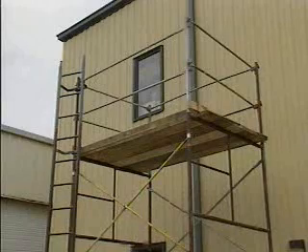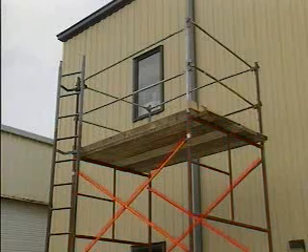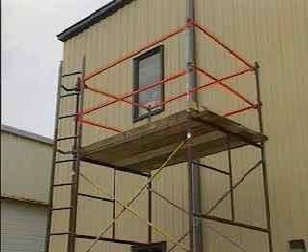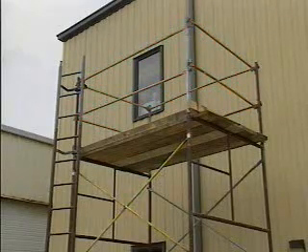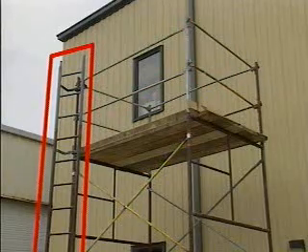Basically, a tubular welded frame scaffold consists of prefabricated vertical end frames, or bucks, and diagonal cross braces that fasten between the frames. Horizontal members are attached between the upper end frames to serve as guardrails. Access to the top of the scaffold is provided by a ladder that's built into the vertical end frames or attached to them.